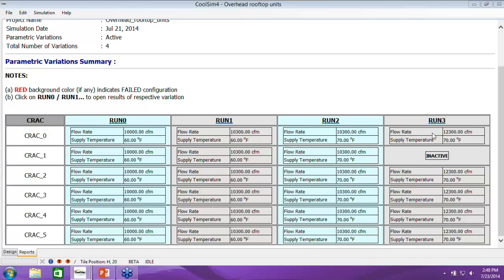And then I wanted to see what happens in a failure case. I ran one with one out to see, and here what I did, assuming we had some kind of VFD, is to run the supply up. These are the supply flow rates here to make up for the fact that one of them is off. So I incremented them by enough, just about, 6. I did 2 each, to be able to supply enough capacity to handle that case in the failure mode, assuming we had a control system on there that would do that. So let's take a look.